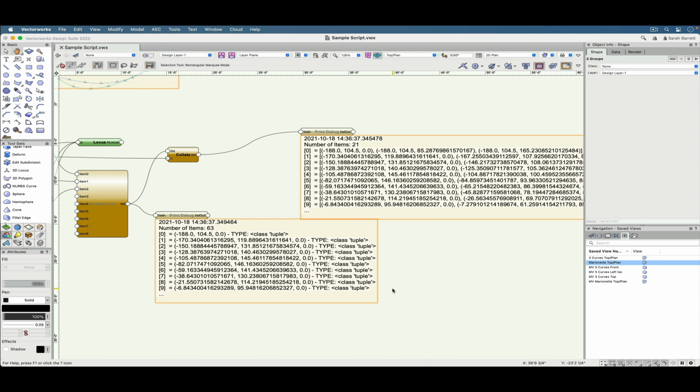If you look at the first value of the collate node, you see the first value from the ordered list node as well as 2 more values. These values are inside of brackets and then separated by commas. Brackets signify lists. Lists and tuples are a little different in that lists can have values added to them, subtracted from them. They can be arranged or manipulated in lots of ways while still remaining lists. Tuples must be exploded in order to be changed.